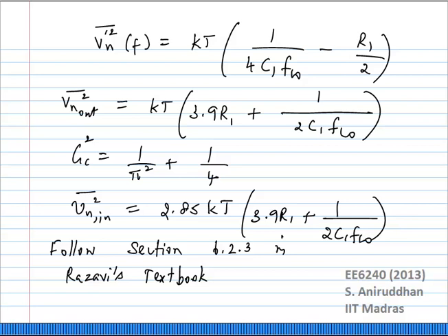Okay, so really most transmitting mixers are still active mixers, because the passive mixers do produce a lot of other components which need to be filtered out very carefully. The second reason is, in a transmitter you normally want to get some gain. You may start off with a very low amplitude, maybe 100 millivolts, and at the end of the transmitter you may want an output power which may be several tens of milliwatts or hundreds of milliwatts. So you can't just afford to use a passive mixer which may just have very little gain or just some loss. You may be better off designing an active mixer. Okay. However, in terms of flicker noise, the passive mixer can be much better.